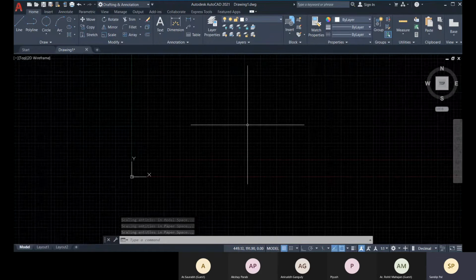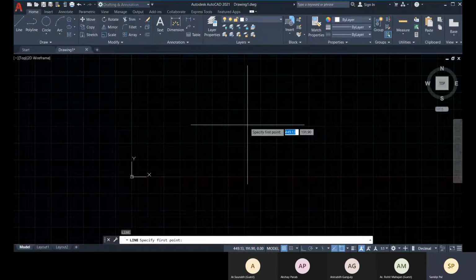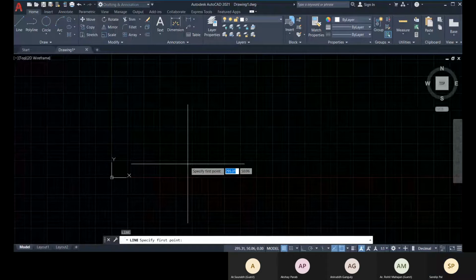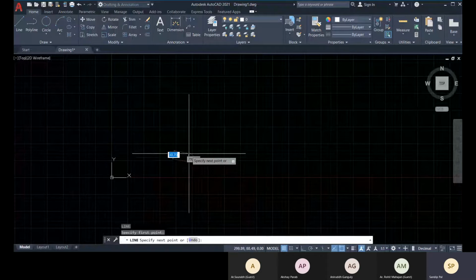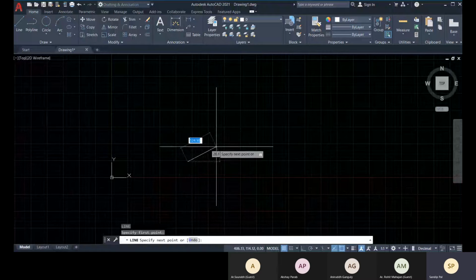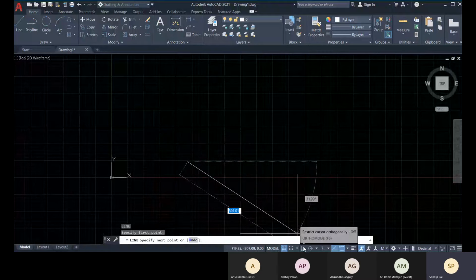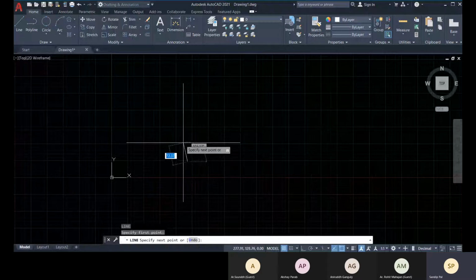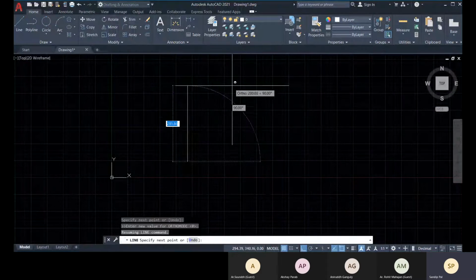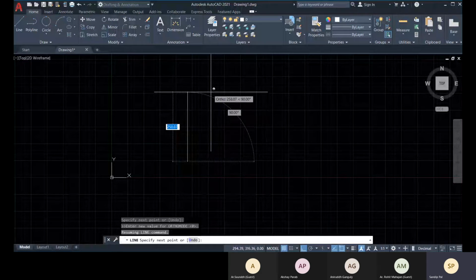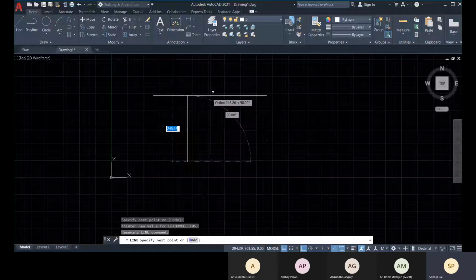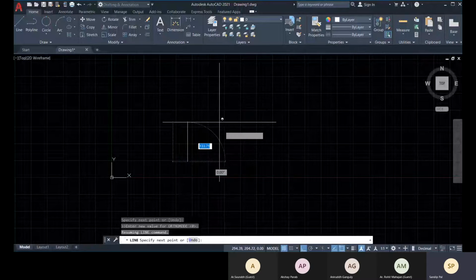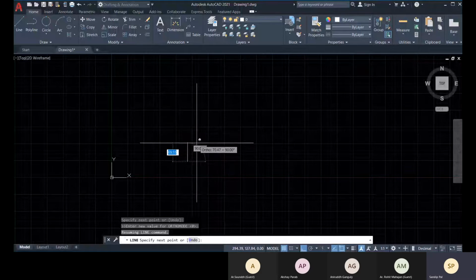And then I will create my door symbol. So first of all, suppose your ortho mode is right now not activated. Even if you press shift, you will get a straight line. See, when I press shift, you check in the status bar that ortho mode is currently on. If I release the shift button, it goes off. So with the shift key you can also work.